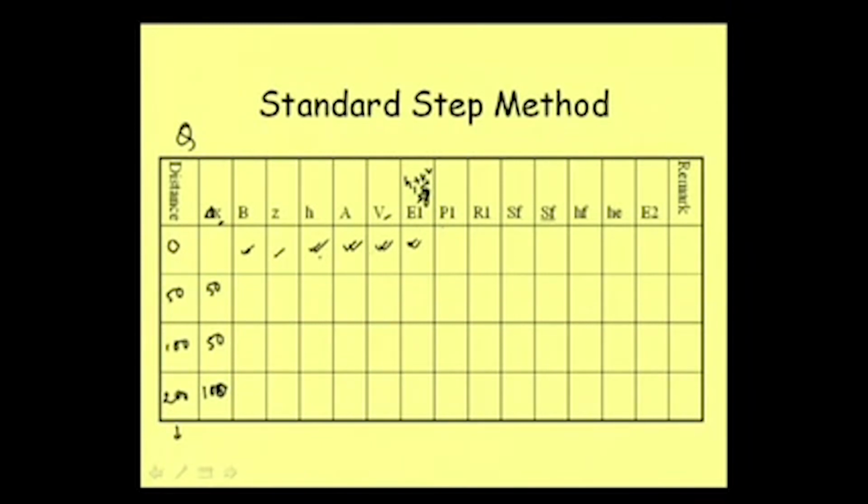Then from all these values we can calculate the perimeter at this point, and we can calculate the hydraulic radius at that point, because area and perimeter are known. Then we can calculate SF, the friction slope, as I have shown already, by using Manning's formula. But what will be the SF bar, that we cannot calculate at this point. Then we will come to this table, this line again.